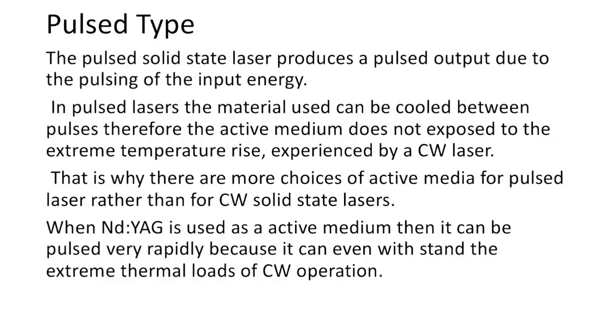So now let's see about the pulsed type. The pulsed solid state lasers produce a pulsed output due to the pulsing of the input energy. In a pulsed laser, the material used can be cooled between pulses. Therefore, the active medium is not exposed to the extreme temperature rise experienced by a CW laser. That is why there are more choices of active medium for pulsed lasers than for CW solid state lasers.